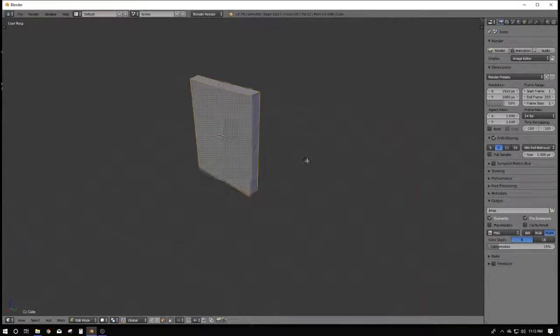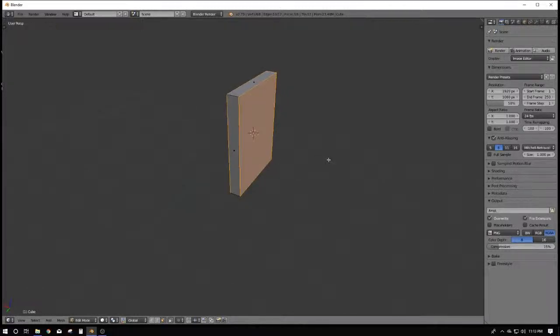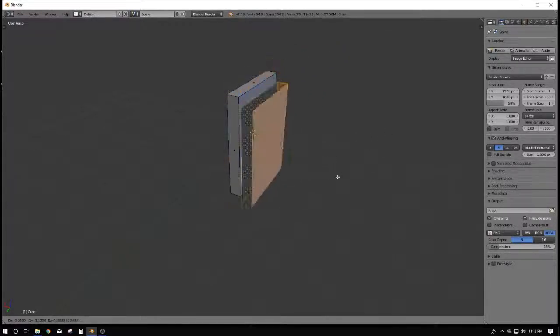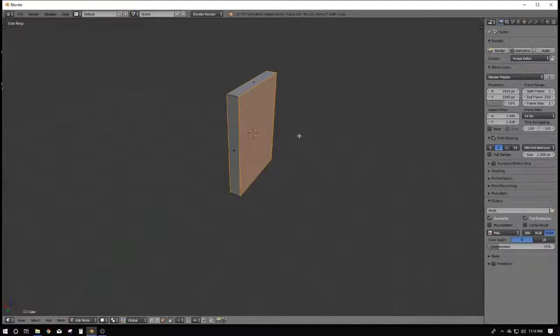So now that we have this, what we're going to want to do is press Shift D. Now what that does is it duplicates those faces. Right now it's locked to our cursor movement, which is fine. We don't want to click somewhere outside of where this is because we'll have to get into snapping back to this object. What we want to do is press escape. That will leave these faces selected, which we want, because we have another command that we want to press, which is P, and that is to separate.